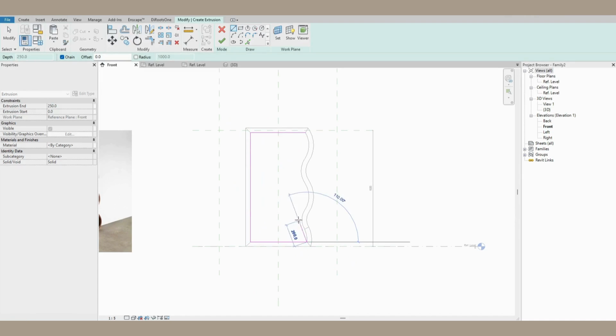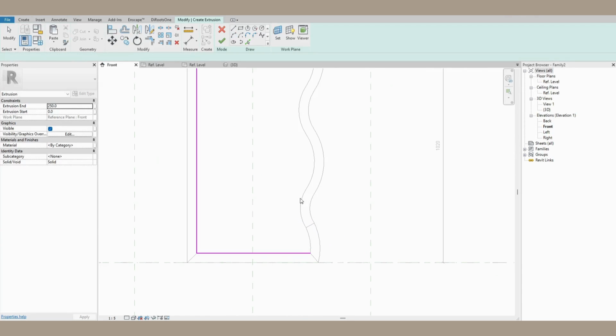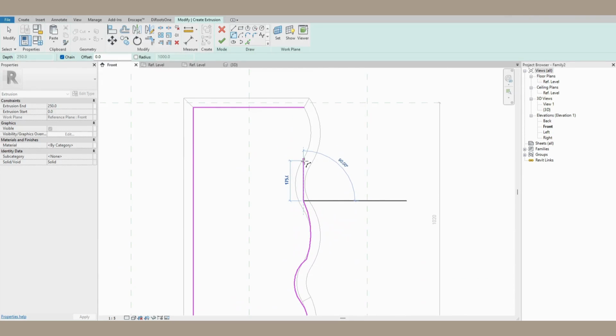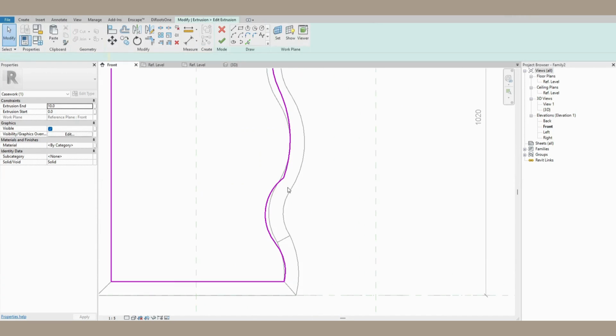So you want to pick your arc tool and maneuver the mirror into the frame itself as it would be inset in real life. And just go with it. Don't be too pedantic about this process. As you know, you will not see the actual mirror itself. It'll be covered by the frame. And then go back after you've clicked the green button to create the shape and maneuver it a bit more to the shape that you want. Always check it in 3D because that's what you'll be seeing if you're doing this for render. So just open up your 3D view, tilt it in different directions, make sure it's exactly what you would have wanted.